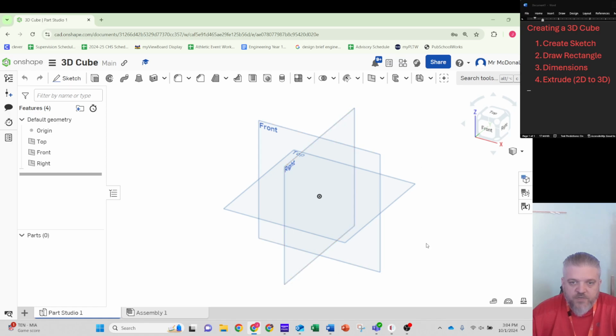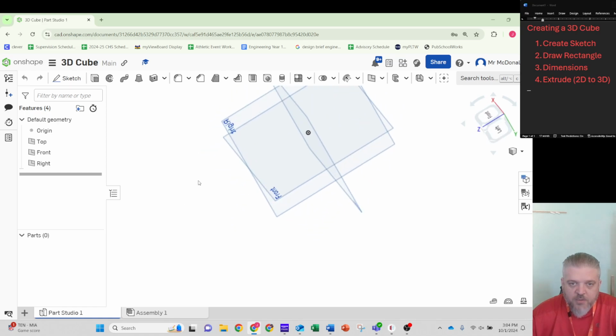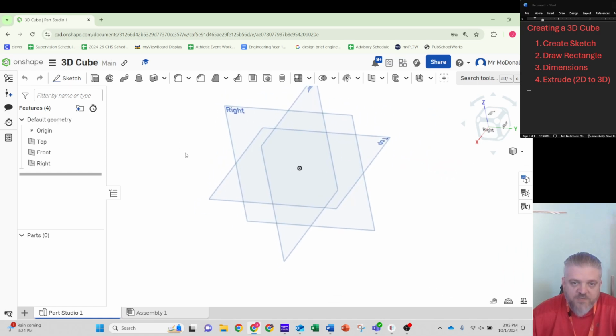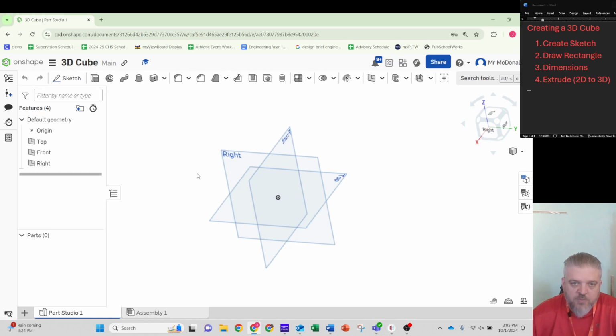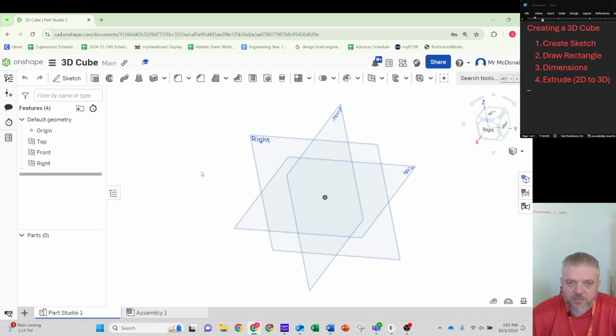So you'll notice over here we got a 3D workspace. I always encourage you to use a mouse so that way you control easier. Left clicking just kind of does a select all. If I right click, I can spin and rotate the 3D, which can very quickly get confusing. If I use the mouse button and click in and drag to the right or left, it will shift up and down, left and right, and the mouse wheel zooms in and out. So if you're a video game player, you're probably used to it, but for those who aren't big video gamers, at least on a PC, it might be a little bit different.